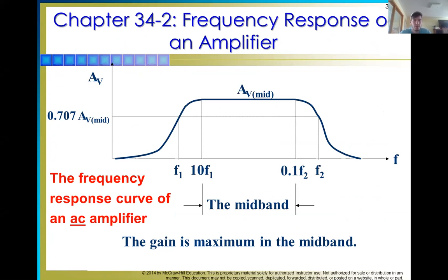Well, here's what I was talking about. There's your overall frequency response of an amplifier. You'll see it's a weird looking little camel hump there. The way to look at that is what's allowable. F1 would be our beginning, because that's where we're allowed to pass through. Any frequency below that would be rejected by this circuit. And F2 here is our maximum upper allowable.